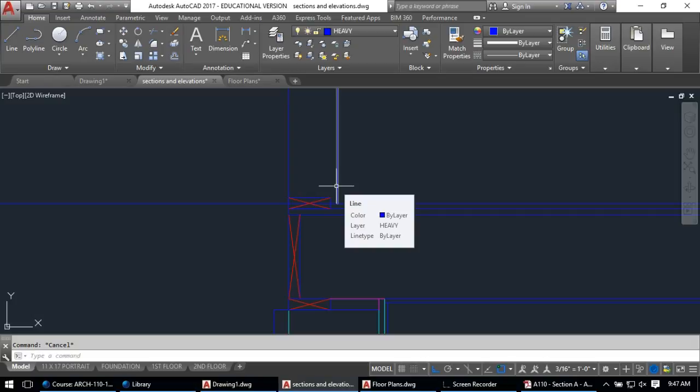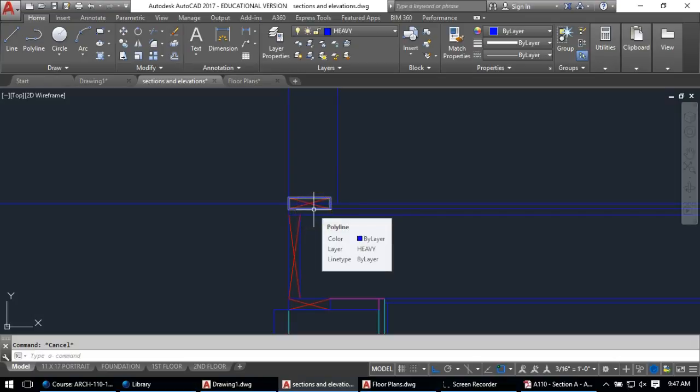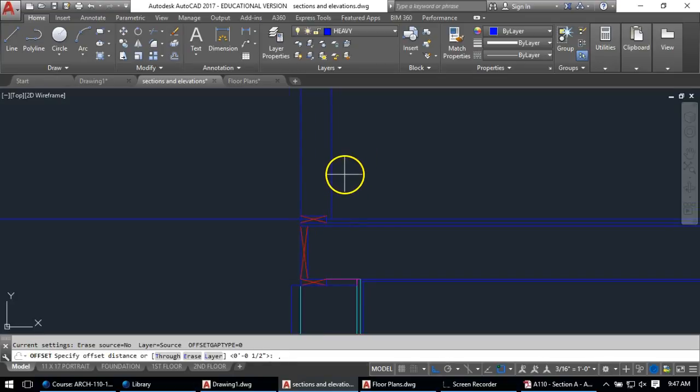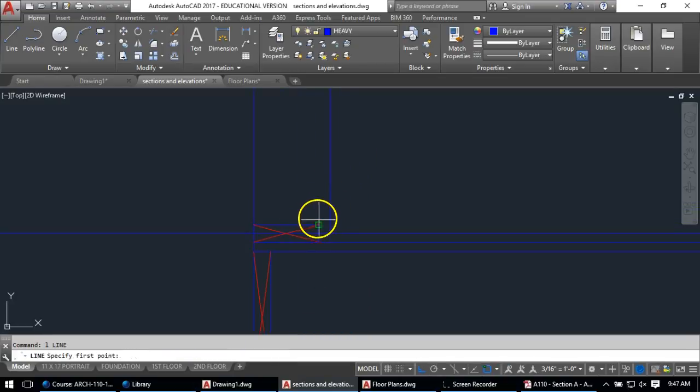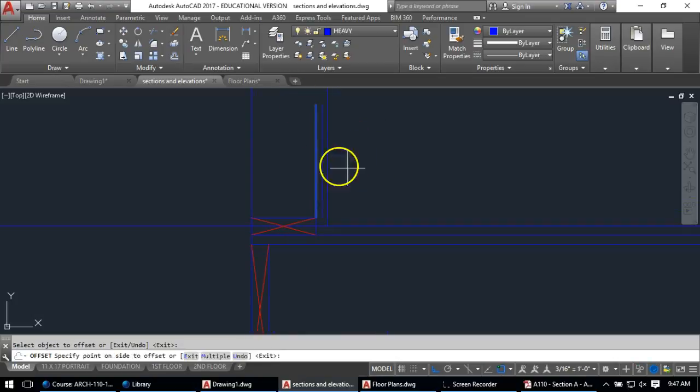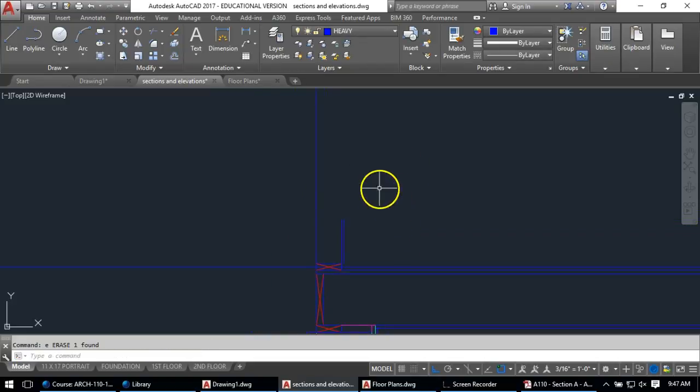Let's see, I'm assuming it's still going to be a 1/2 inch drywall. Yeah, 1/2 inch drywall. And actually, yeah, 1/2 inch drywall. It's interesting because this wall thickness is different. Looks like it's going to be drywall internal edge and an offset 0.5. See, the difference between my real construction face and what I drew there is a 1/2 inch. So I'm going to erase that inside face.